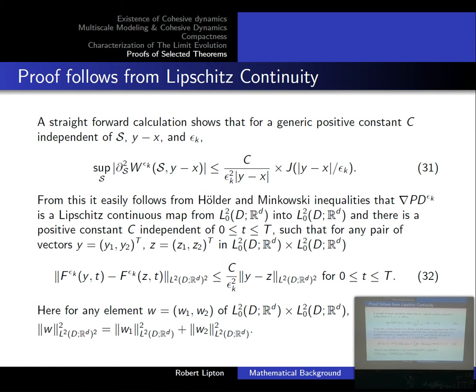Again, you will be able to show that these Holder solutions, as epsilon goes to 0, converge. Again, you can find compactness, and there's a subsequence converging strongly in L2 to a limit, which lies in SBD. Okay? So it's very interesting that you really don't need discontinuous functions to begin with in your peridynamics, which from numerical simulation means is good. You'd love to have smooth functions, and you can approximate them nicely. Okay? And then in some limit, yes, you get a crack. So in a sense, this is going to be a regularized scheme for computing cracks.